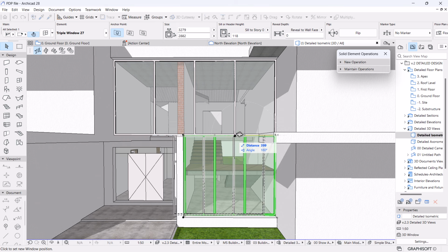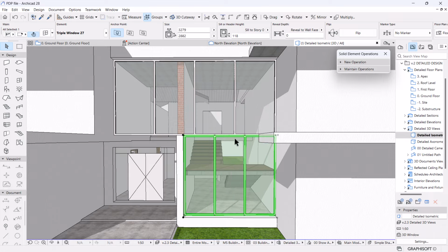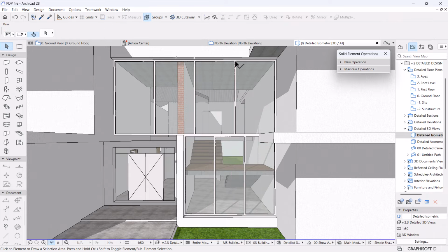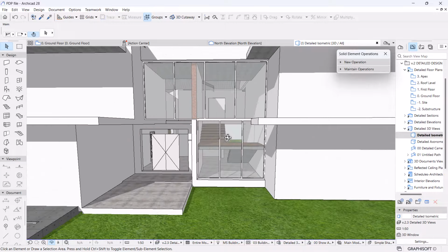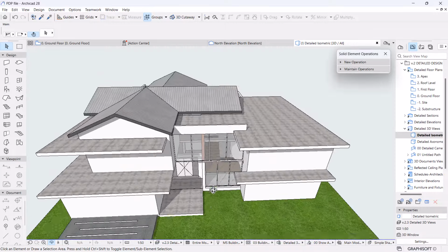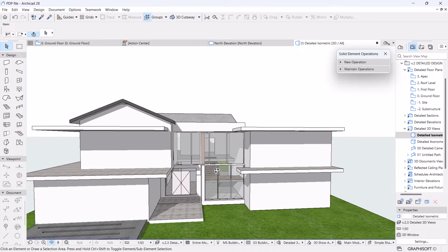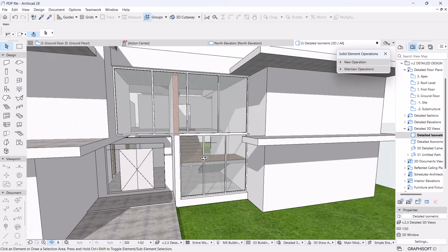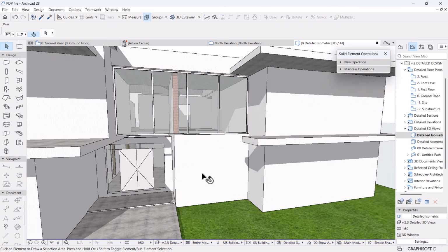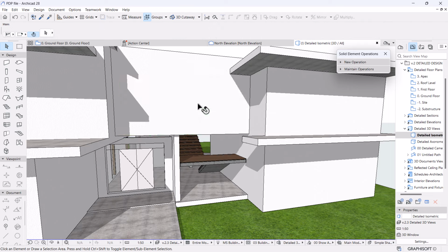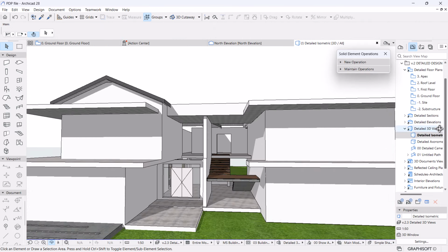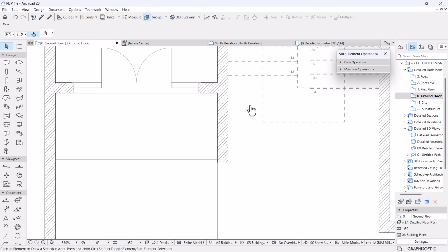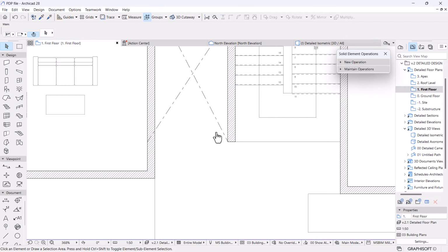Okay. So I'm not sure with this one, can we move the, I don't think so. Can we align these frames? But clearly we cannot align the frames. So the best way is to use a curtain wall. Right, let's use a curtain wall. I'm going to get rid of this, get rid of the wall, and that, also the wall. Then we remain with the opening.